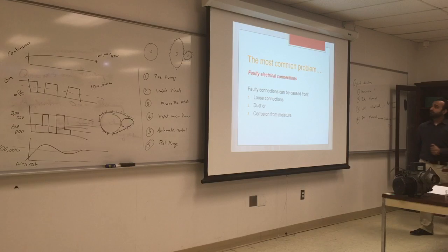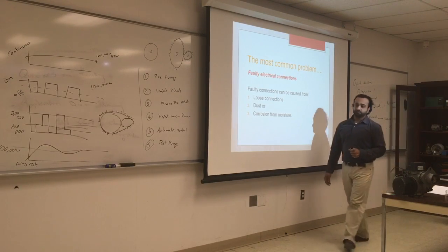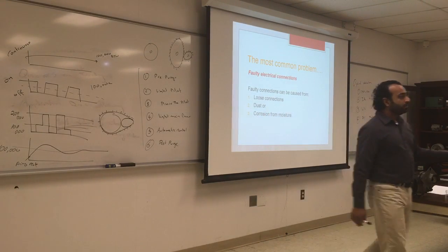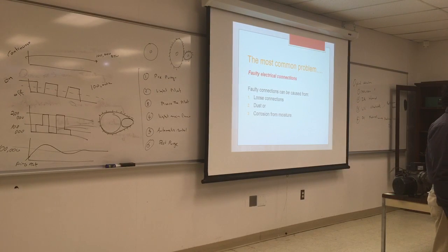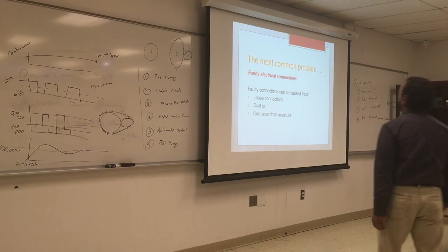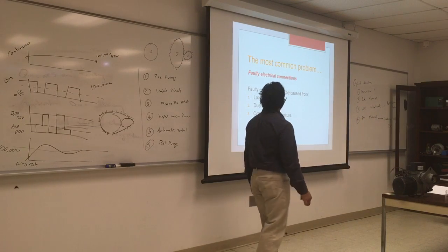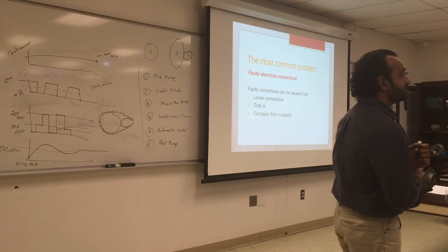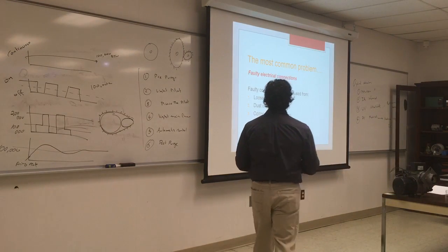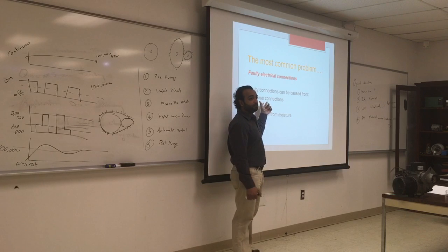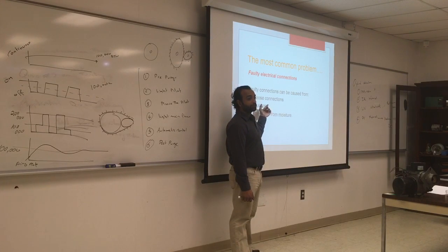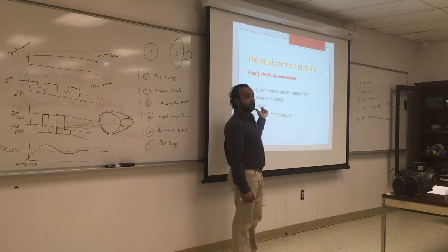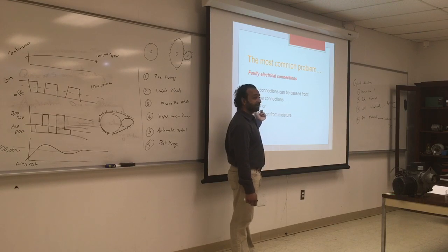Okay, so some of the most common problems when it comes to the modulating control motor, or MDM, and firing rate control are faulty electrical components. We see that a lot. There's something that's not connected correctly, mostly loose connections, they do come loose. So always check the wire nuts and check the wiring for integrity. Those wirings are press fitted. You don't find a lot of wire nuts.